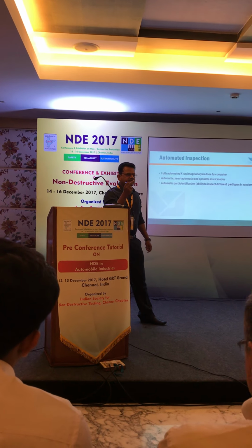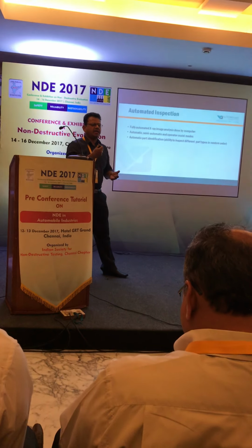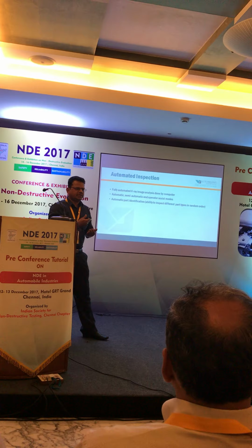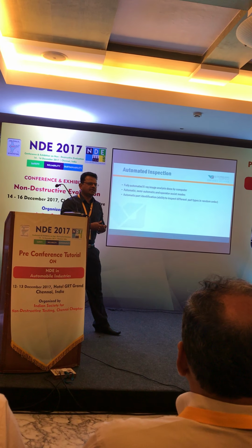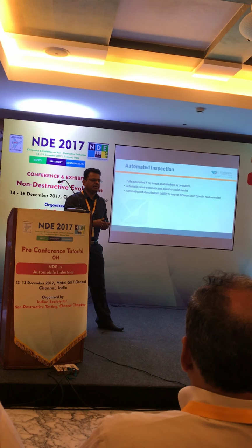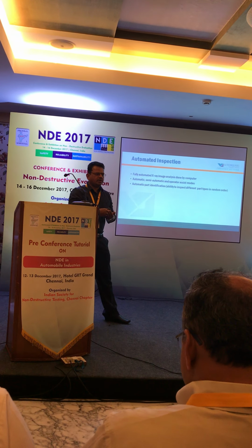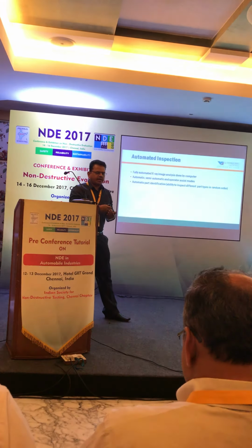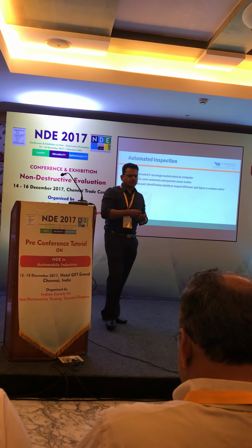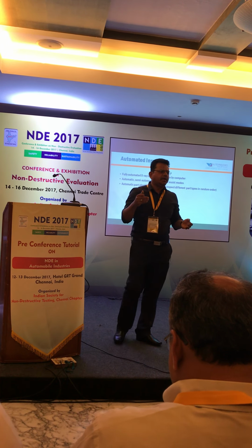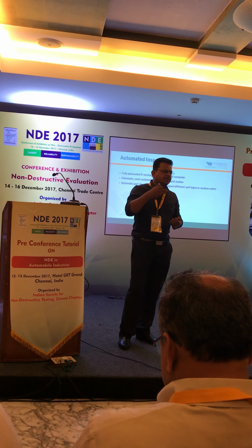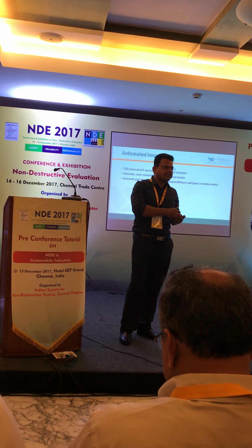At the greater thickness, we have an IQI to see the sensitivity at the higher thickness, whether we are able to achieve the sensitivity. And the positioning of the robot, the angling or the position of the robot. So a lab test is done, and then at the customer end, it is implemented the same.